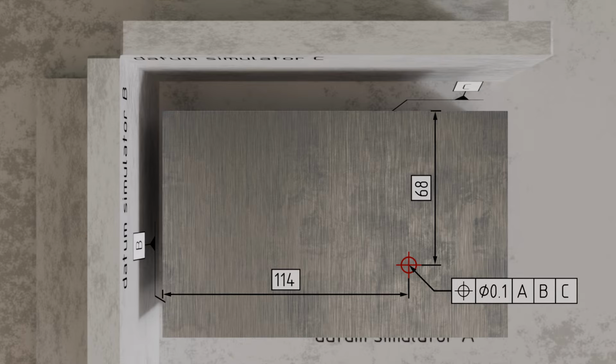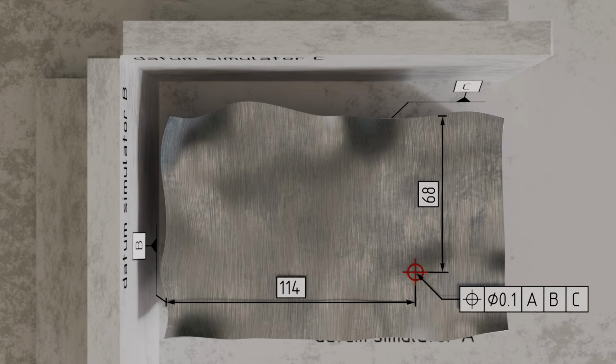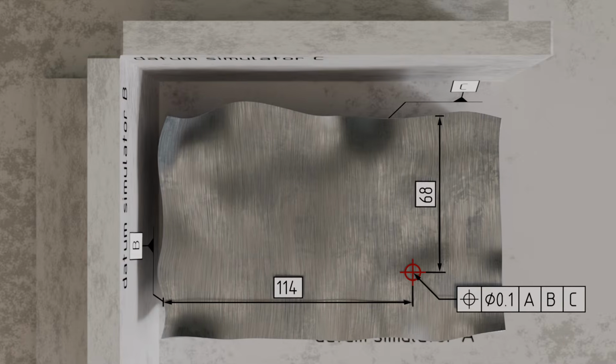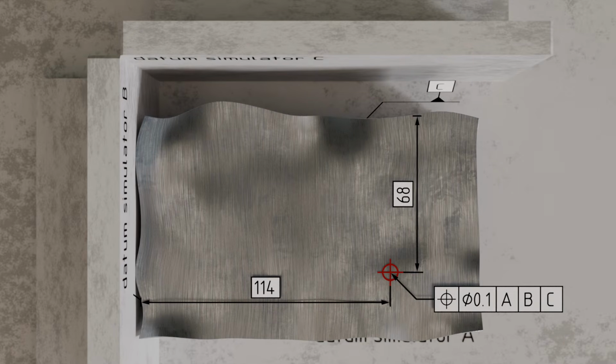However, since in reality we do not have an ideally shaped part, the order of alignment does indeed make a difference. To illustrate this, consider the exaggerated real shape of the part shown, which is uneven and skewed. Since, in our case, the left side surface of the part is the secondary datum surface, this surface must be aligned next. We therefore slide the part with this datum surface B onto the corresponding datum simulator B so that it no longer wobbles and is firmly fixed on this reference surface by at least 2 points of contact.